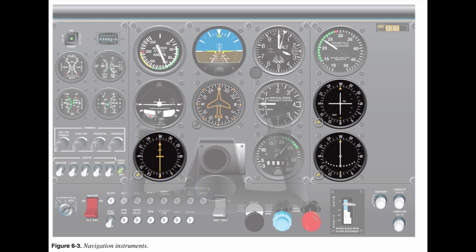2. Trim, fine-tune the control forces until control pressures are neutralized. Trimming for hands-off flight is essential for smooth, precise aircraft control. It allows a pilot to attend to other flight deck duties with minimum deviation from the desired attitude. End of page 6-2.